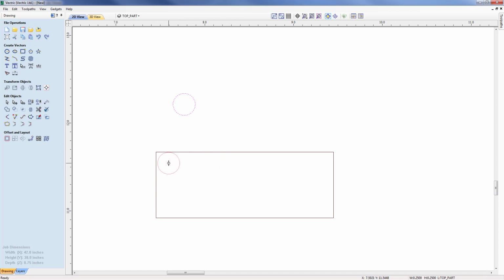So it's going to come along now, and it's going to get to that corner, and it's going to be leaving a radius of material in that corner, which means the tenon will not fit into that area. Okay, so we're going to need to make a modification to this. Okay, so I'm going to delete that out now. So we need to essentially allow the tool to come into the corner and create a little bit more extra room to allow the tenon to move into it.